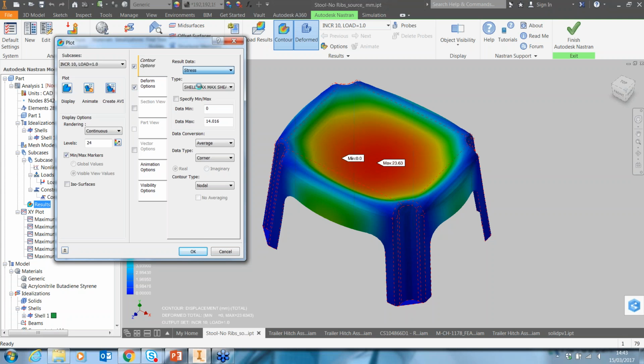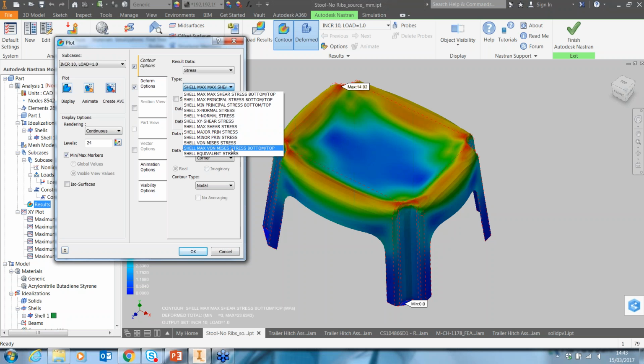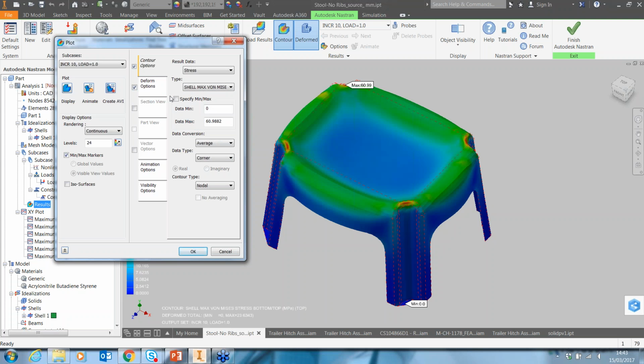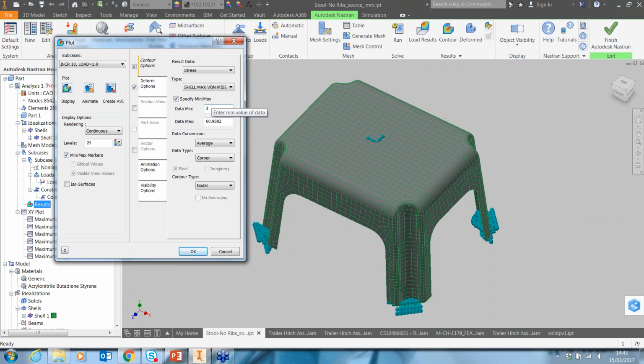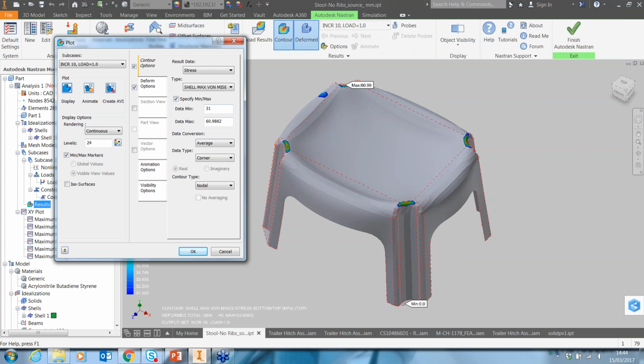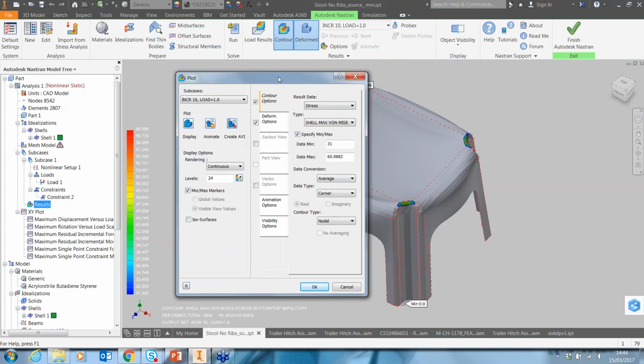If we look at the stress, the stresses have come down, and if we look at what's above the yield strength, we can see just some tiny areas on the corners, and that's all. But this design is now giving a totally different result to the linear analysis. So this design should really be acceptable compared to the disaster that we first saw when we ran linear static. So the results can be very different.